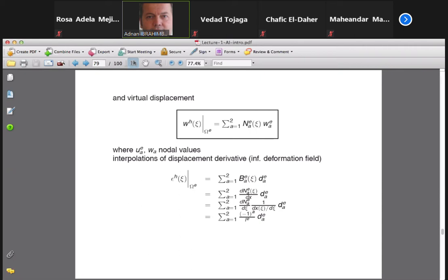So in other words, the strain is still the displacement at one end, this is displacement 2, minus the displacement at the other end, which is displacement 1, divided by L, which is precisely the definition of the strain. Hence, we did not really change the final result. We have just changed it into something that looks more complicated. Well, it looks more complicated to a human who is used to doing this little computation by hand.